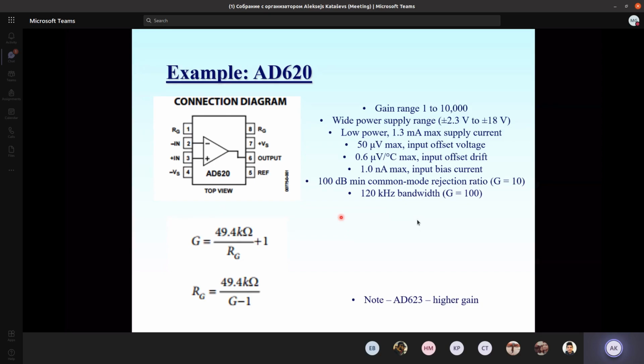We very seldom need more than 20-40 kilohertz of bandwidth for biological signals. Yes, it could be used for ultrasonic devices, or in a high radio frequency range where the bandwidth goes up to megahertz. But for biological signal measurement, it's a very, very good solution.